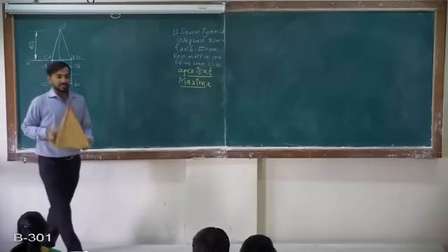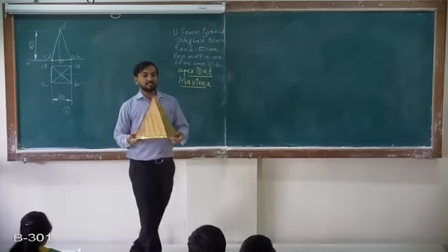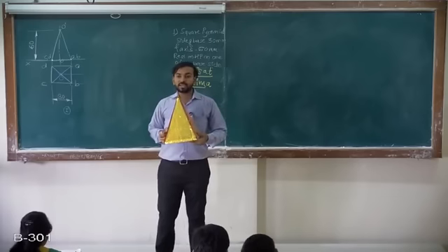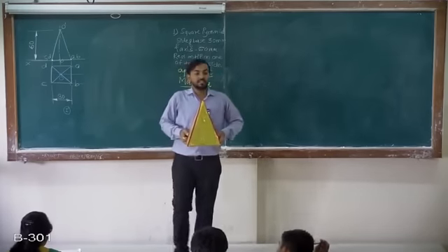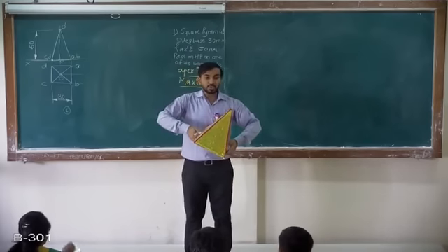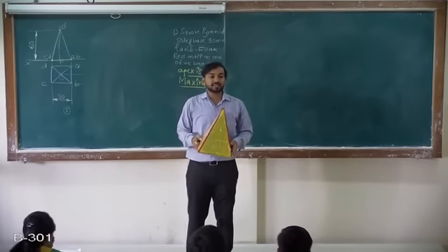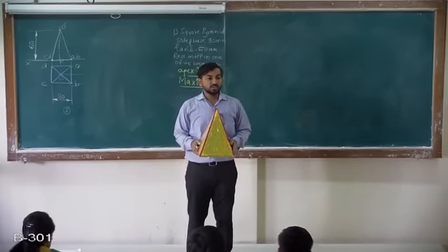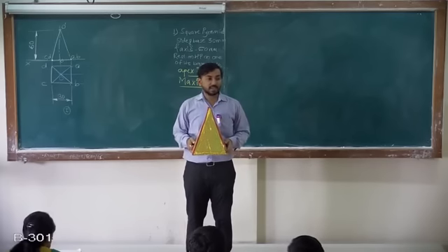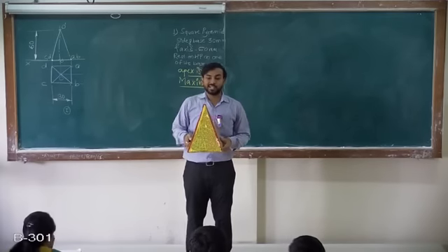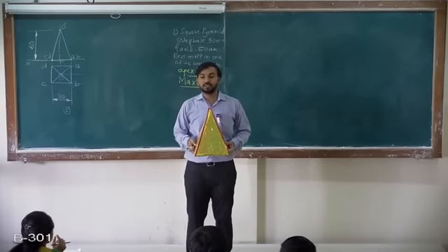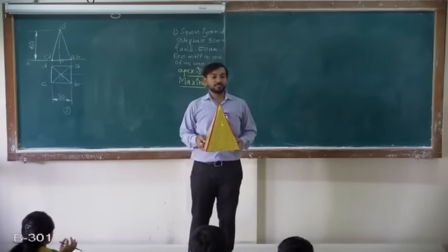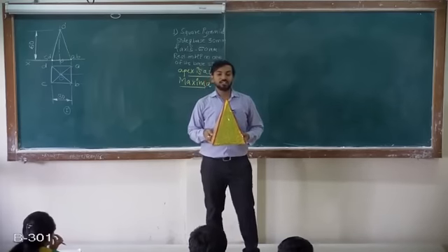So let's say this is the first stage, this is a phase. Apex maximum position, we are keeping the first condition constant, resting on side. So it is inclined to HP so that apex is at maximum position. So can you imagine what is the maximum position of this apex when it is inclined to HP? Or is it the same case which I am showing on HP? So I'll show you with the diagram.